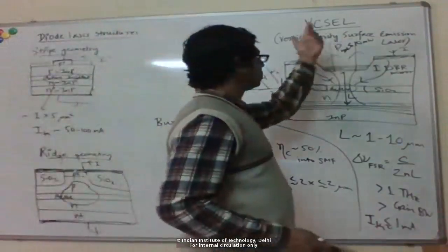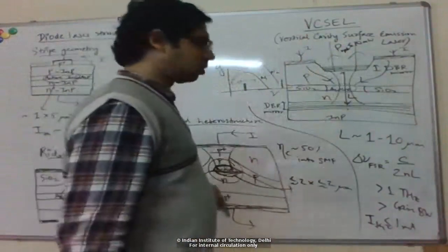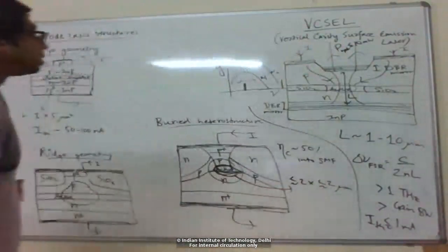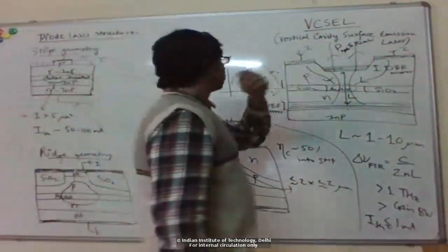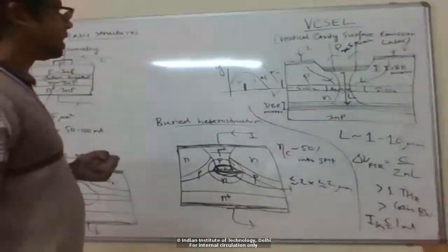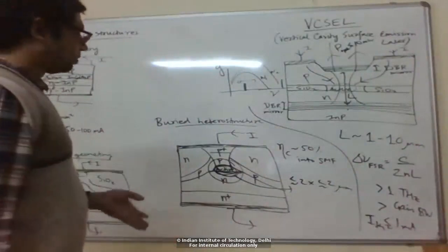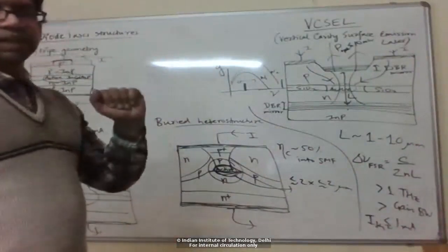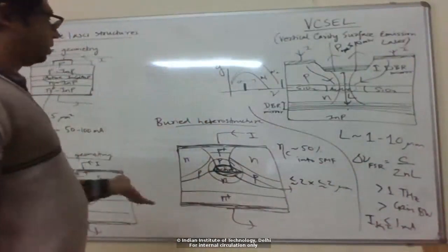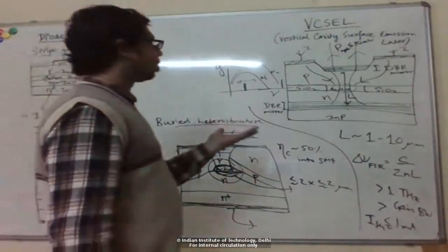For LEDs we also derived this L-I curve, right? For a given input current, how much optical power do I get out? Similarly, we want to do this for the laser. One difference we'll see is that the laser characteristics will be nonlinear. For the LED, we saw that it was just a straight line relationship, so the power coming out was directly proportional to the current. But here we'll see that the characteristics will be nonlinear,